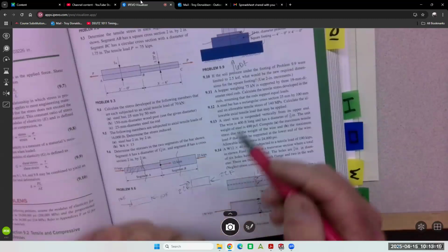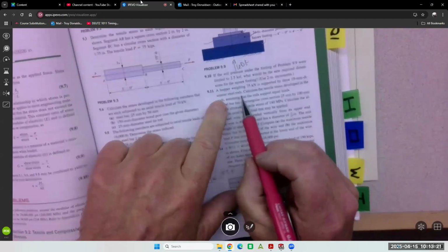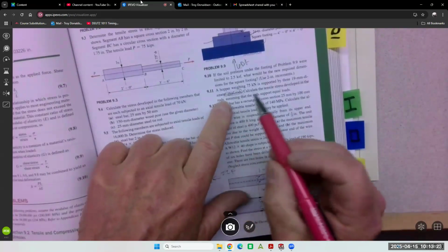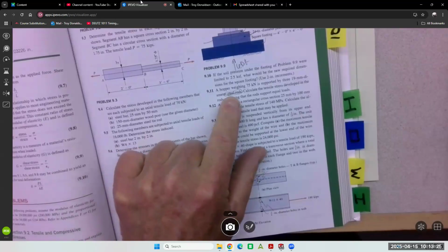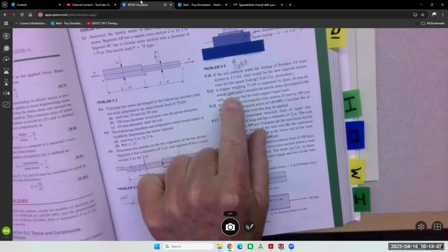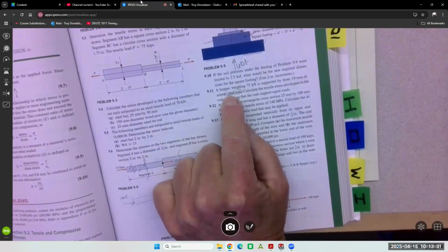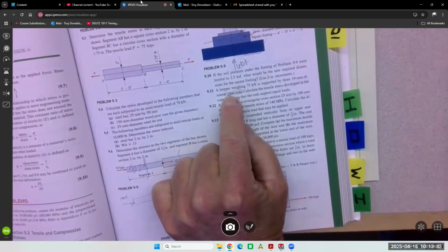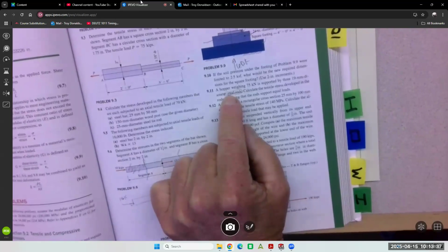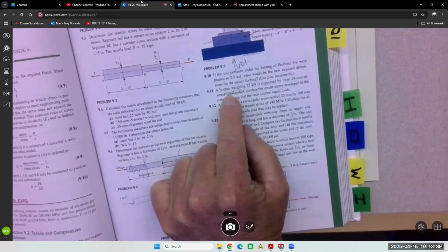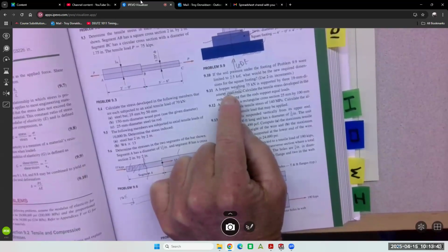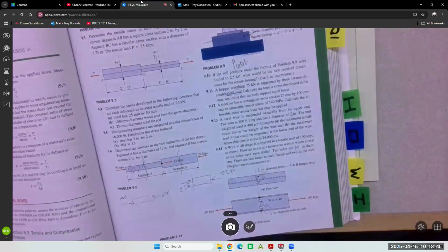And what did it say it's made out of? Steel. What's our limit for steel? I think it's 250. 250 megapascals, and you're coming up with 88. So we have a factor of safety of 3-ish, right? 8 times 3 is 240. Yeah, so we're about in the 3 category.